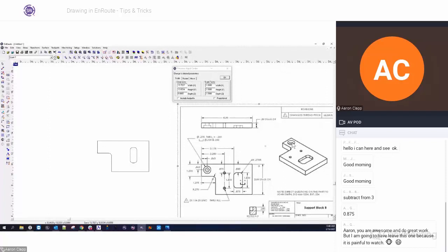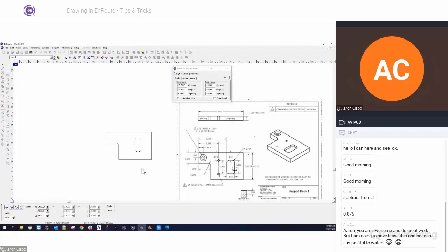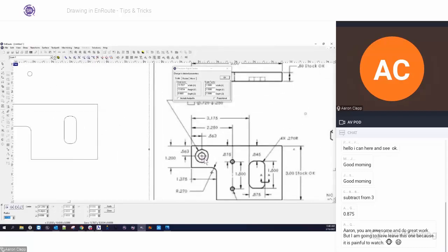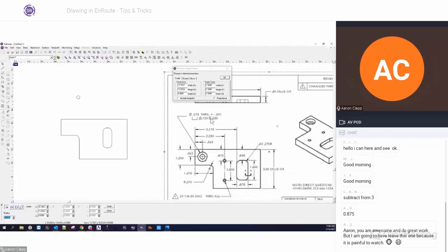a hole that's going to be going down, according to our drawing, 0.25 inches in depth. And then the rest of it, the center, is going to go down the full 0.5 inches. So I'm going to create two circles. Our radiuses on this one are going to be 0.125, based on this drawing here. This is the diameter that they have listed here. So diameter 0.25 is the center one, so 0.125. And then the outside hole is 0.375, so that's going to be 0.1875.